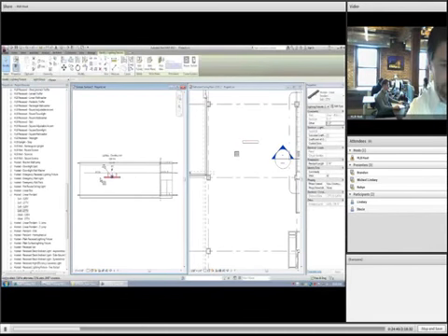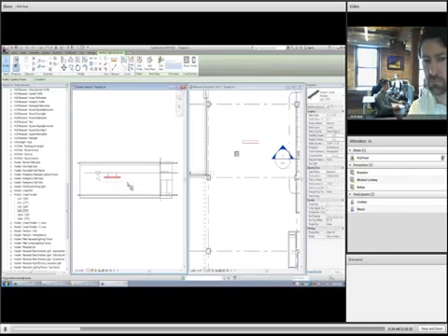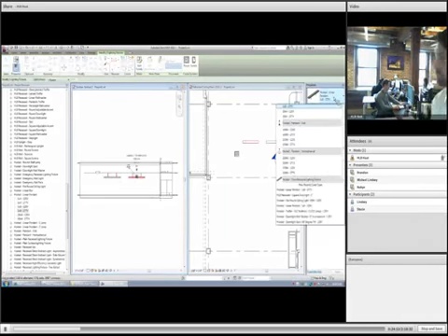So the question that I would have in this method of documentation, my understanding of reference planes and levels, which I could be wrong, is that even if you draw a line that's only an inch long on the screen, it acts as if that thing goes to infinity. Correct. While we're locking that to the bathroom ceiling that's at 8'8", let's say in our initial design, the bathroom ceiling's at 8'8", and so is the public corridor.